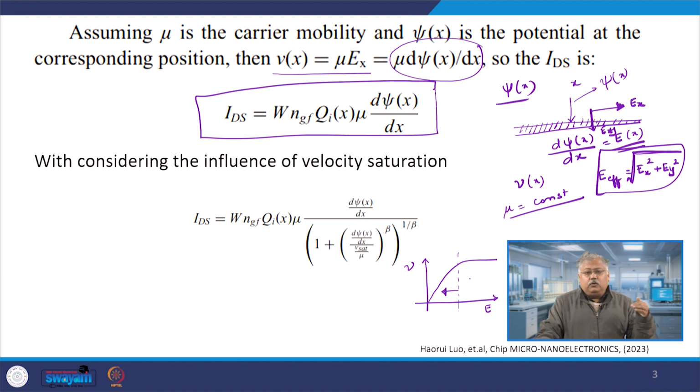Then as the electric field goes on increasing, the velocity goes on increasing, which is by first principles, which we already know. But please keep in mind, as the velocity goes on increasing, the amount of scattering also goes on increasing, because the electrons are encountering more fixed ions there, so scattering becomes larger, and therefore the drag also increases, and therefore it does not simply go on increasing linearly.